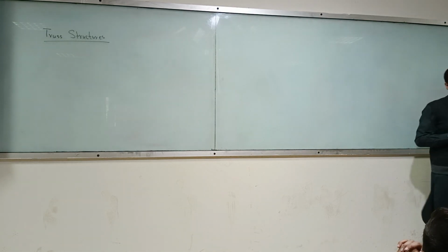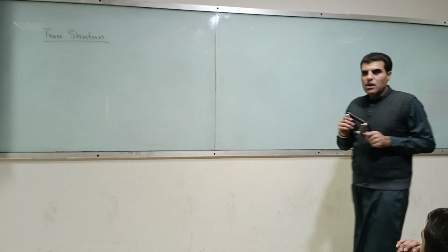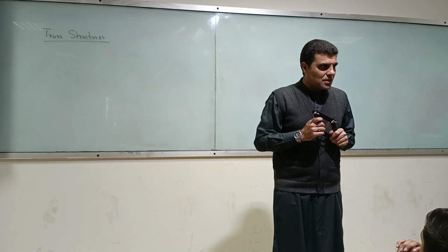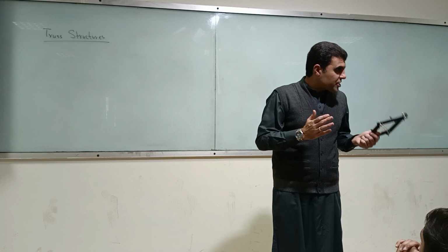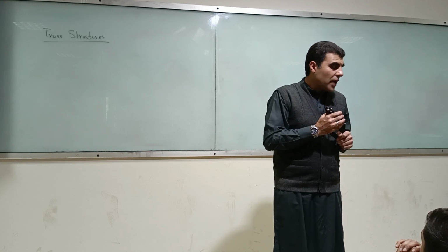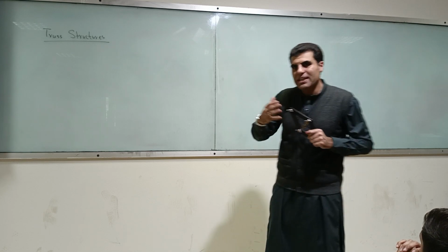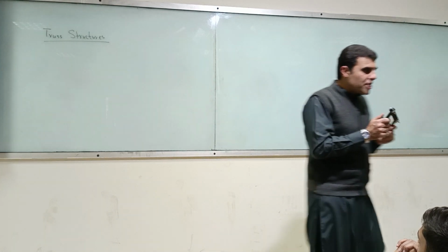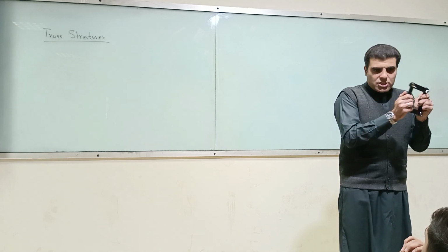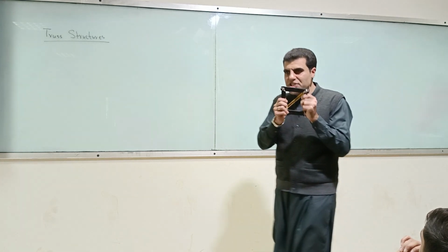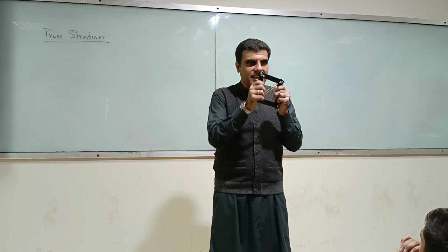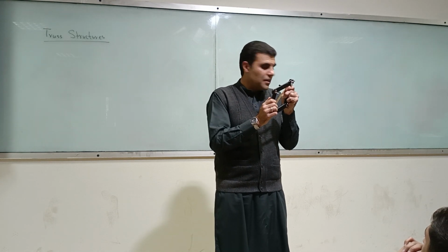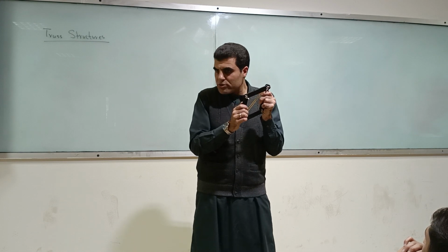Normally the trusses are made out of steel. And why is that? Yeah, because steel is very good in tension. Steel is good in compression also, but comparatively it's good in tension. So if you arrange your links in such a way that they take tension, that is an efficient use of the structure, isn't it?